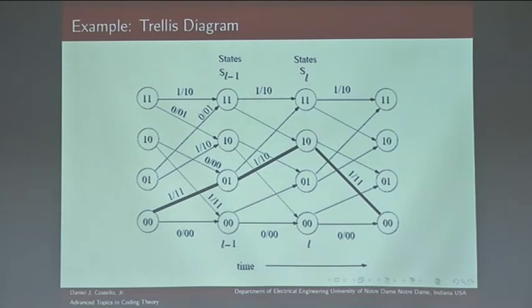And in other cases, in turbo codes, the encoders that you use for turbo codes really need to be feedback encoders. In the case of high-speed modems, it's convenient to use the feedback form of encoder, but it's not necessary. It makes some of the analysis easier. But in the case of turbo codes, it's essential that you use feedback encoders, systematic feedback encoders.